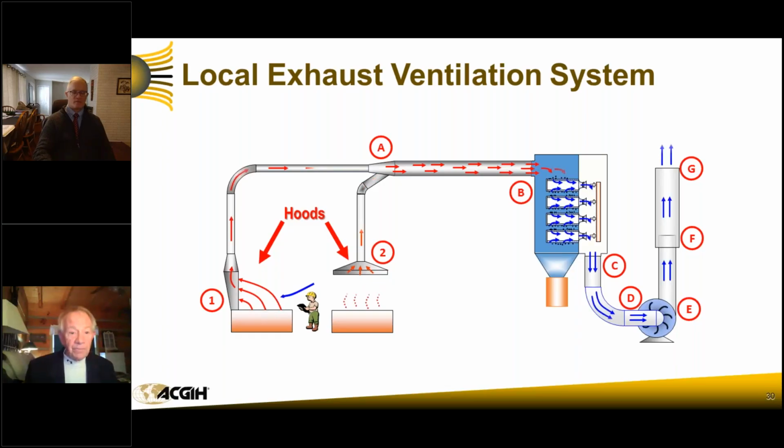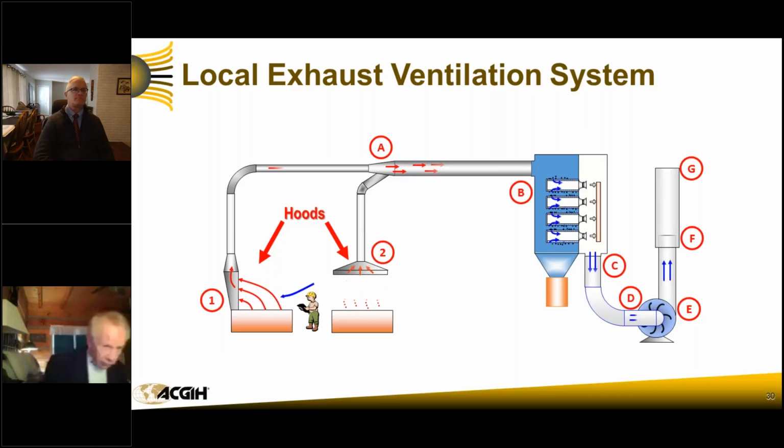In this case, we have an employee who, when he takes his notebook and goes over and looks very closely at this degreasing tank, is going to find out that he's going to get a face full of degreaser, and whatever that contaminant is, that's not a good thing. So canopy hoods are not our favorite hood. Sometimes, especially with hot processes, we have to use them, but we're very careful about that. As industrial hygienists and industrial engineers, we like to take the contaminant away from the breathing zone. As a matter of fact, we like to go down in a way whenever we can.